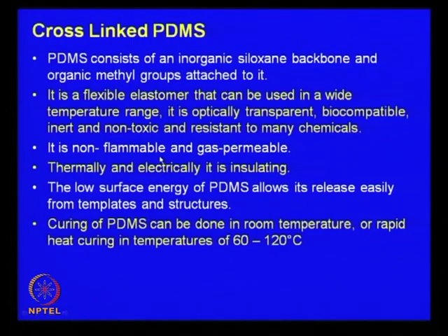PDMS also offers very low surface energy. That makes it suitable for two things: direct fabrication of hydrophobic surfaces, as well as use in soft lithography, particularly in molding techniques, where its low surface energy makes it very easy to detach from the patterns you have created